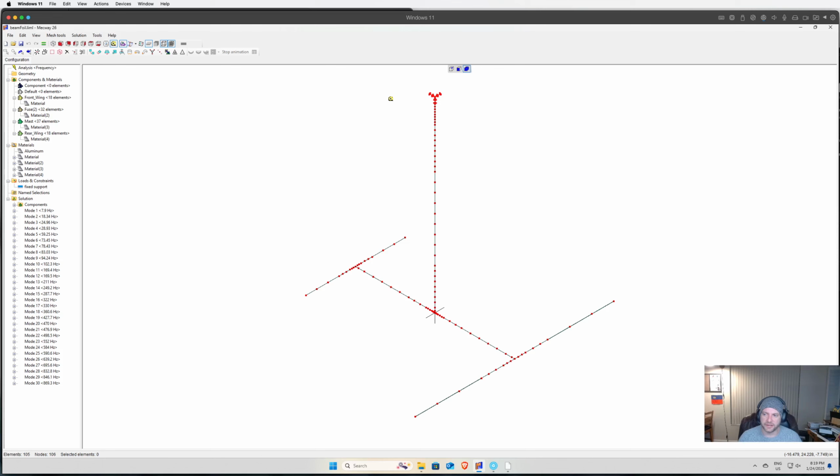I've done it a lot in ANSYS and Abaqus. Actually, more in Abaqus, but also in Nastran when I was working in the aerospace industry. There are a lot of stick models like this built, where we actually built all the models by hand. And so what I did was I gave this pure rectangular beam properties in the model.